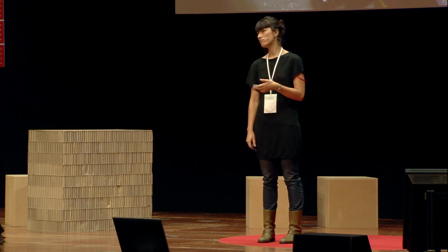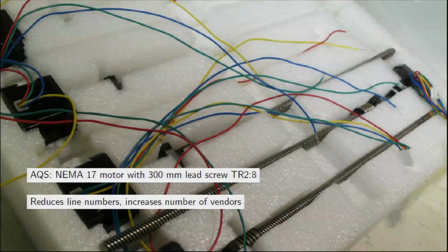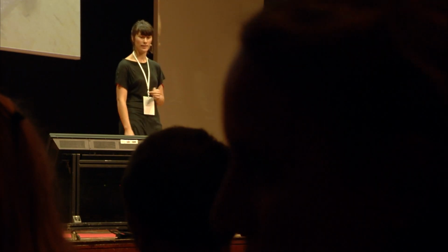with custom tooled bits. So these are some motors that I ordered, and they have an integrated lead screw in the stepper motor, and they come with a wear compensating lead screw nut, and they're 4-start, which is super baller. One of the things that it does for small format milling machines like the MTM Snap is reduce the number of line items on your bill of materials. So yes, you're introducing a custom part, but at the same time, now you don't need helical couplings or thrust bearings or other things that you might have if the lead screw wasn't integrated.